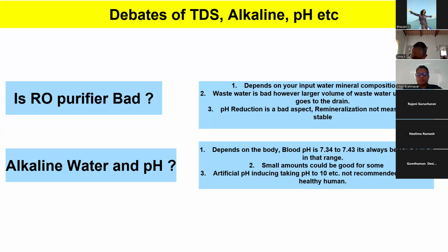So we went to an apartment association discussion, where they said RO is wasting water. But on the STP treated water, they were wasting 50,000 liters of water every day. After treatment, they were just draining it to the drain. What we normally say is, if you are able to map this RO wastewater directly to your STP, it wouldn't harm the STP because it is a very small quantity of RO wastewater. Per capita, with RO, you will end up wasting 10 liters of water. But the same person will waste 90 liters of water completely to the drain without any reuse.